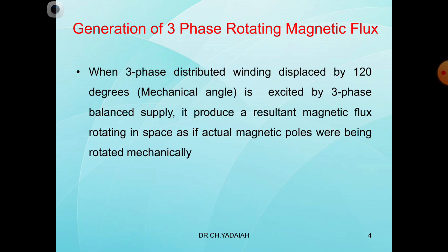As per Faraday's laws of electromagnetic induction, it automatically induces EMF in the rotor damper bars. The rotor bars are closed because both ends are short circuited, and due to the induced EMF in the rotor damper winding, currents flow.